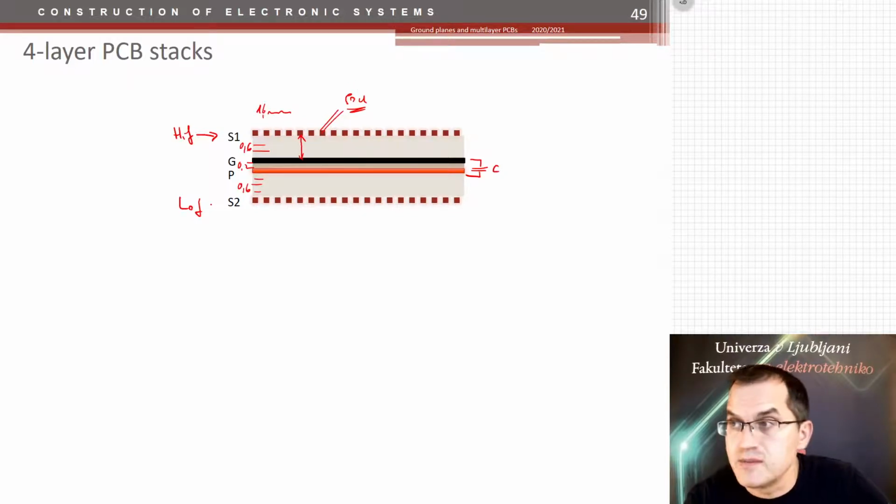And in terms of EMC, of course, we would rather have shorter distance between the track and the return ground plane for minimizing the ground loops. So that PCB is not recommendable, actually.